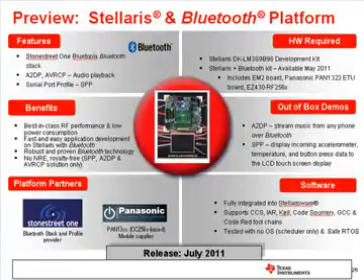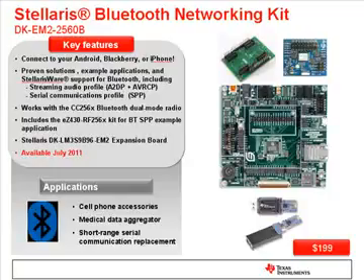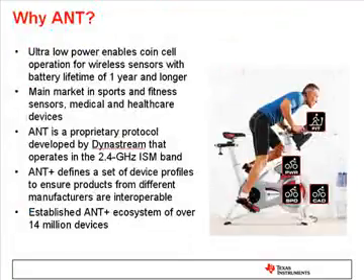I'll touch briefly on ANT technology. I mentioned it towards the beginning as another technology that TI supports. I want to make you aware of it because it's an ultra-low power technology that if you need to enable sensors, this is a great technology to consider. So you can consider this as a type of Bluetooth technology, but that's enabled for very, very low power. The power that's required, in this case, you can get by with a coin cell, and you can have this coin cell operate for 1 year or longer.